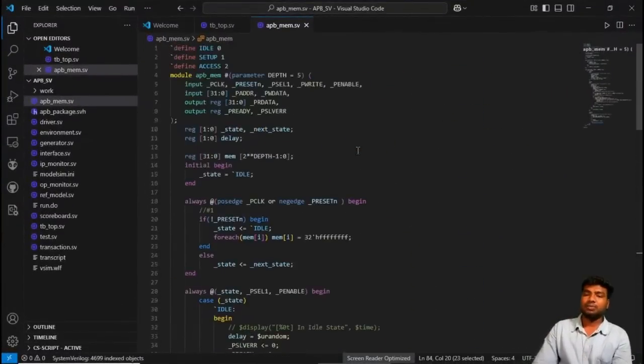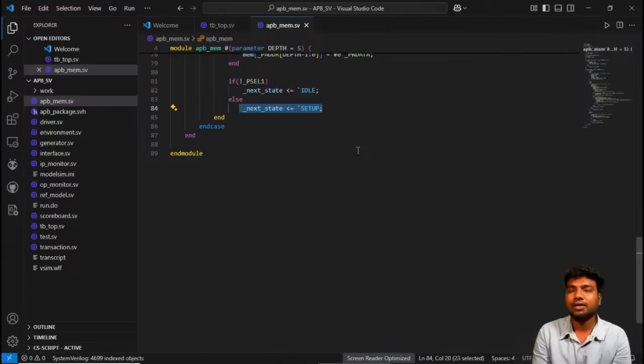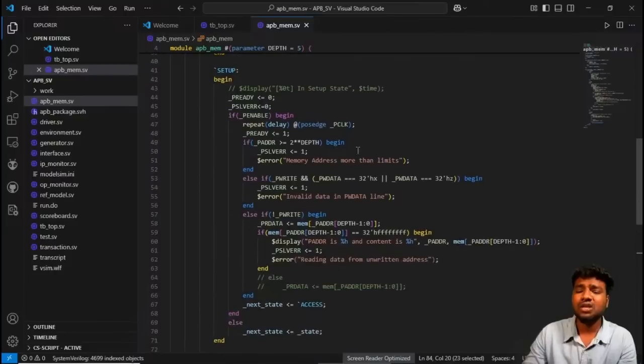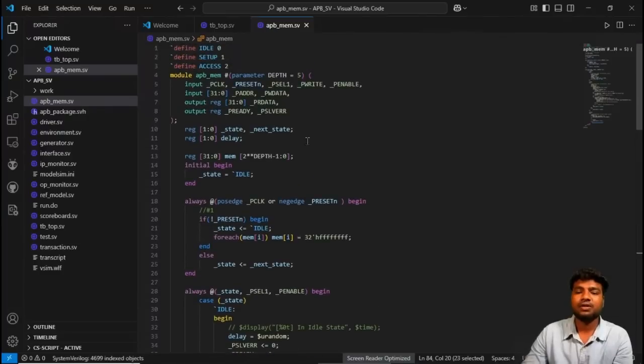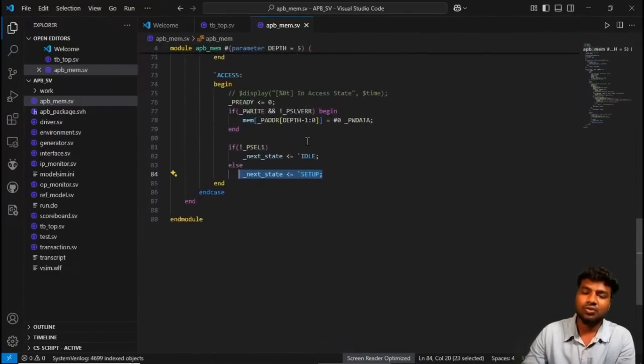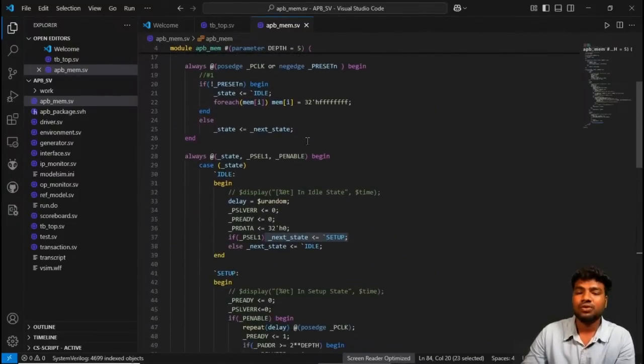So this is an APB code, simple only. You can write more complex logic in APB. This is simple logic only; I am checking the slave error and PREADY. There are additional signals in the APB, so you can refer to the spec on Google. It is open source only, the AMBA protocols. You can try it at your home. After writing this, you can write the testbench code for this.